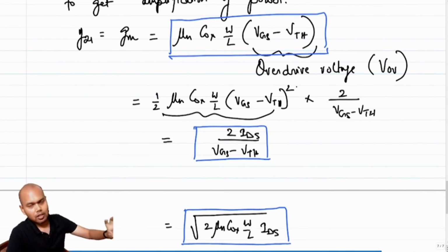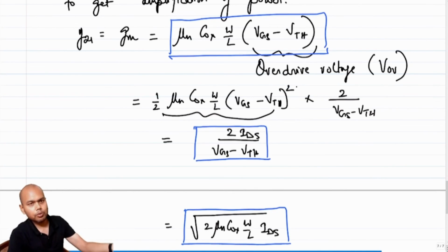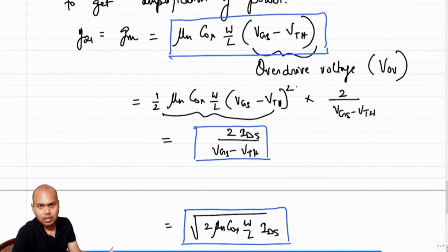So if you have set up your MOSFET in the way we have set it up, you have applied voltage between the gate and the source, and you have generated some current IDS, and you now say that I am changing VGS, but I will use the second equation and I will keep IDS the same, whatever it was earlier. Then obviously you are doing something wrong, because the moment you change VGS minus VTH, your IDS will also change.